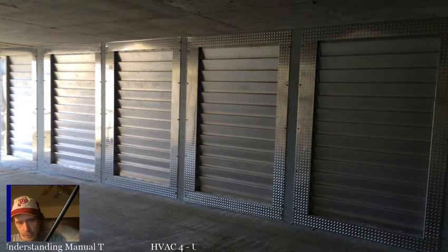You could have a dirty air filter. You could have a dirty blower wheel. You could have too many vents closed, too many dampers closed, anything like that. You're looking for issues that will restrict airflow, because that means the air is moving too slow across the heat exchanger and the temperature is rising too much. So that is what you're looking for on a piece of equipment that cycles off on the limit switch a lot. I see this a lot in VAVs, actually.